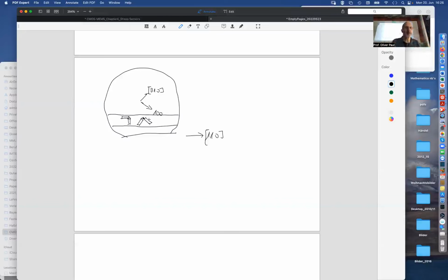And well, that would be something which is a mixture of a bit of, I mean, in the crystal coordinate system, a sigma. So if we call this X and this Y, this would be sigma X prime, yeah, and there is no sigma Y prime applied to such a bending structure, and then it is equivalent to a bit of homogeneous expansion, and then a bit of difference of sigma XX prime minus sigma YY prime.